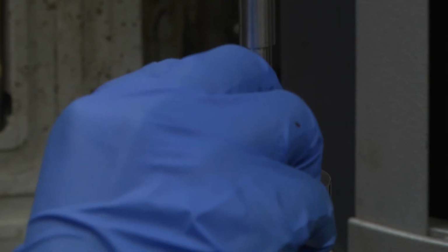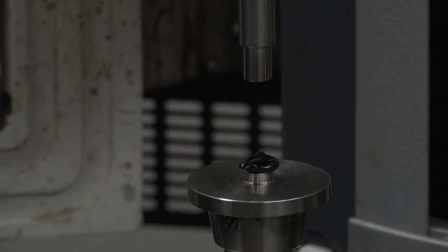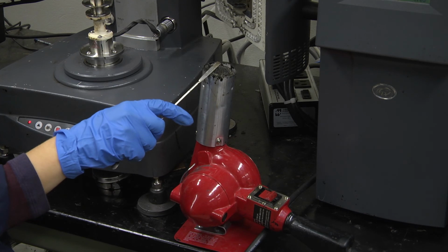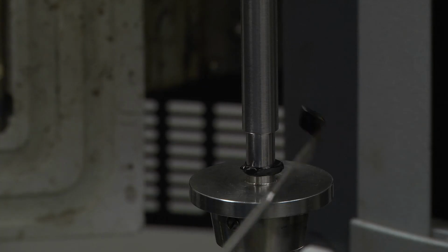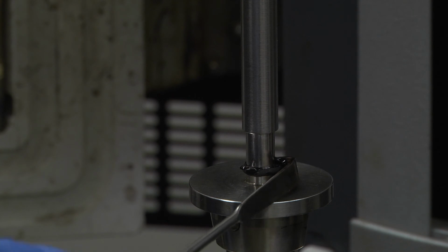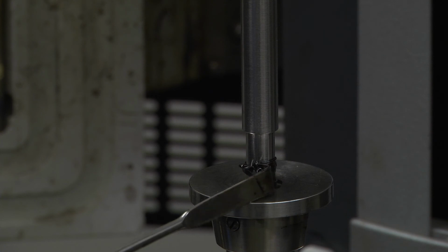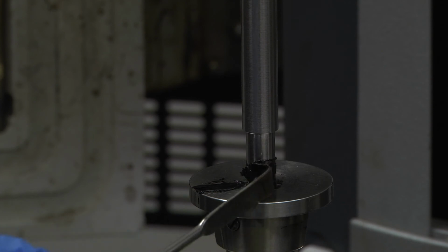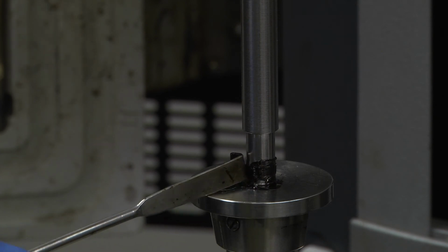Raise the DSR upper plate and place the asphalt binder sample on the lower plate. Lower the DSR upper plate to the trimming gap, which is slightly higher than the test gap. Use the spatula to trim the specimen around the edge of the test plates using a heated trimming tool. This step is critical as the DSR calculates stresses and strains based on an assumed sample height and diameter. Improper trimming can alter the specimen diameter and thus lead to erroneous records of stress and strain.